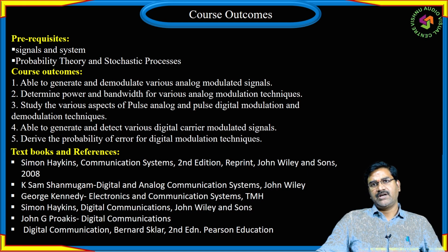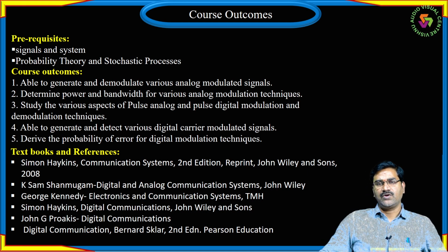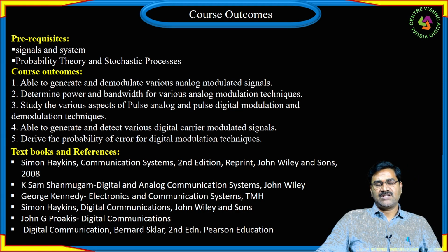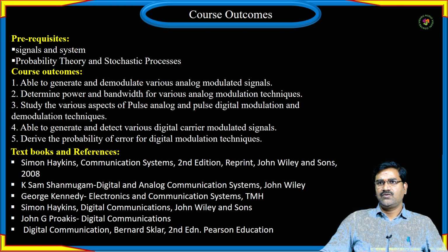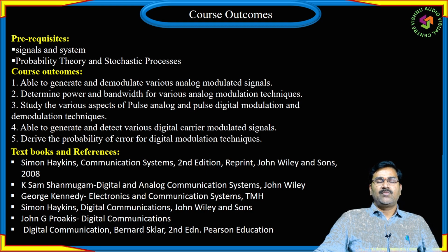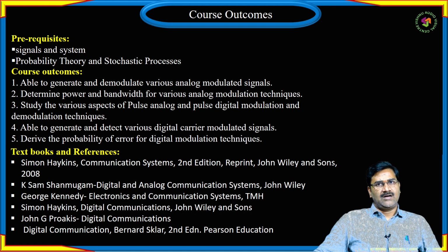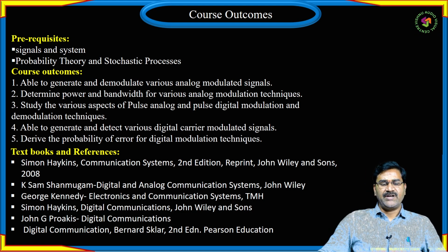Thereby it will be extended to digital modulation schemes, where you will study various modulation schemes such as ASK, PSK, FSK, which are used in modern communication systems. And then you will be analyzing the probability of error for the various digital modulation schemes, so that the performance of the system can be analyzed by using the probability of error as well as the bit error rate.